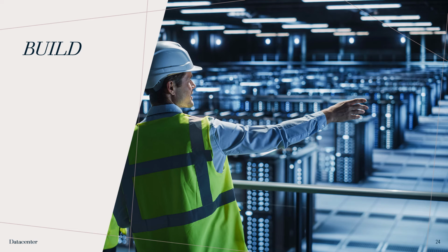Uninterrupted access to energy is the alpha and omega of a data center. That is why data centers are built, and why they should ideally be powered by two independent routes of energy coming through their own transformers. The energy goes to the substation through an automatic transfer switch, called an ATS, with a diesel generator connected, and into the UPS units with their own battery modules.